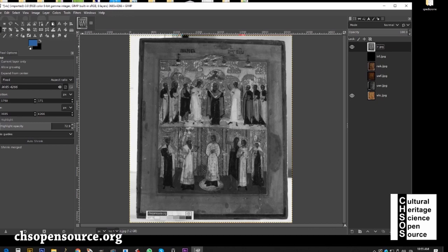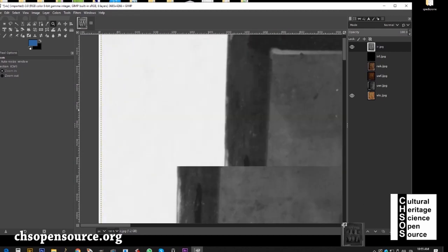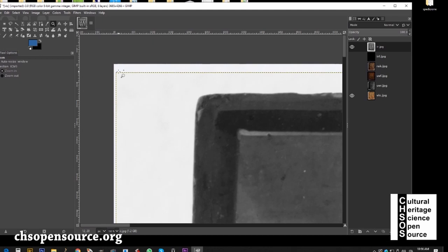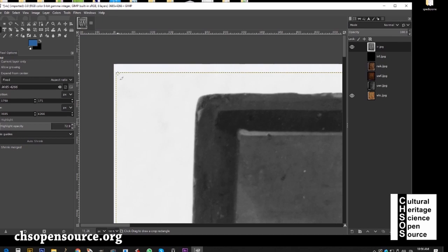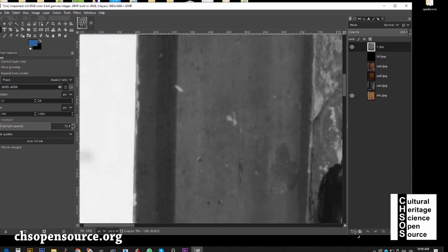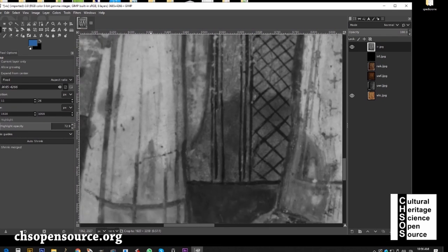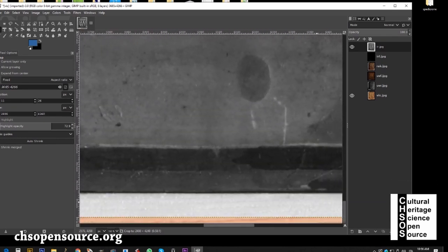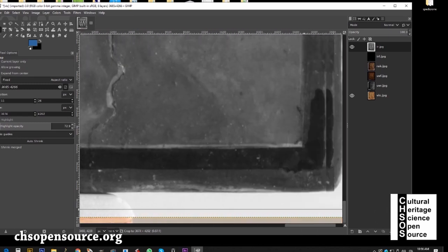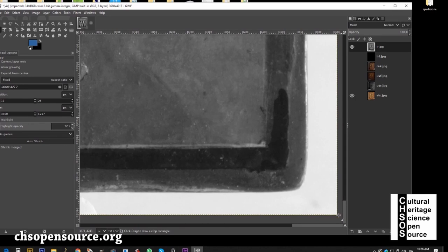Okay, first I magnify, so I go here on the top. Okay, so I see exactly, this is the infrared layer, the lines. So I use this cropping tool and I crop a little bit inside the infrared, so I'm sure that I'm getting both the layers. Okay, there we are. Pretty good. We go here, I click enter, and the cropping is done.